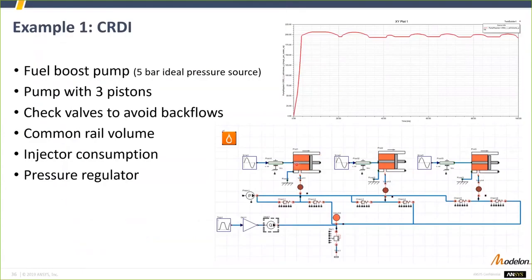of the flow provided by the pump, which gives you some ripples, and also the flow through the check valve, which is a restriction that is not ideal, and so also enables some overpressure. And you see that after some iterations, you have a kind of cyclic behavior. It's interesting to see that the time is in milliseconds, so the dynamic is quite high. I don't know if you can see the time, 40 milliseconds here, 60 milliseconds here.